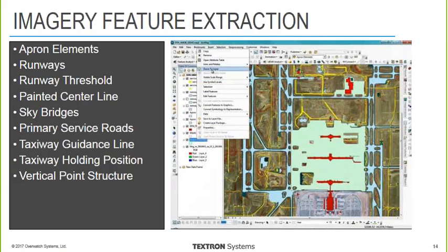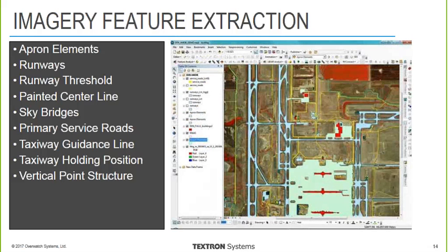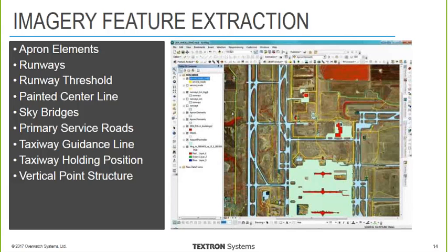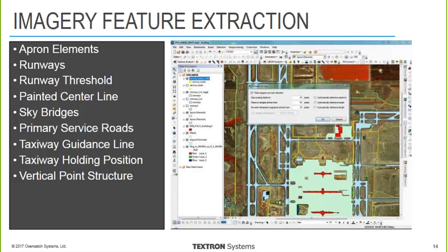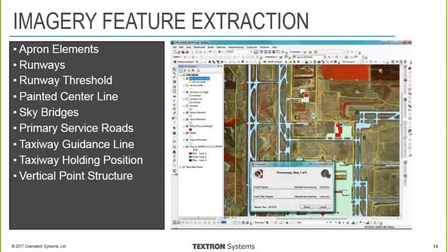And this is basically the process. We just keep working through these features. And so as we go, we're masking them out. We've already got several from the LiDAR data. We can check our attribute table, and you can see the values that we have for that as well. Here we're converting the road network to lines, and so we're able to get length from that.